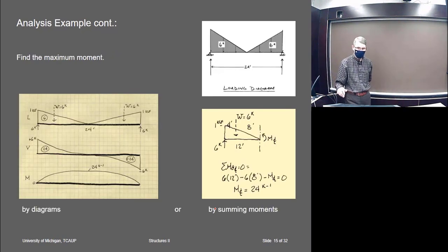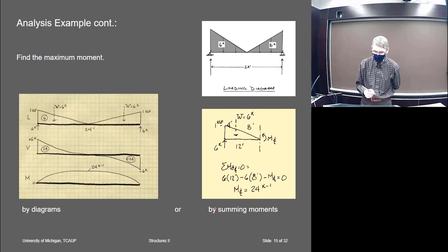Well, okay, then we have to know the moment. Since we're just given the beam loading, we can calculate the moment. You can do these lovely shear and moment diagrams. I guess this is a parabola, right? So this must be base times height over 3.